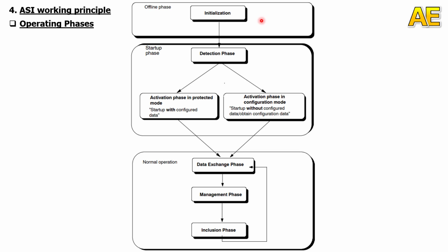After switching on the power supply, the configured parameters are copied to the parameter image, so that subsequent activation is with the preset parameters. If the ASI master is reinitialized during operation, the values from the parameter image, which may have changed in the meantime, are retained.